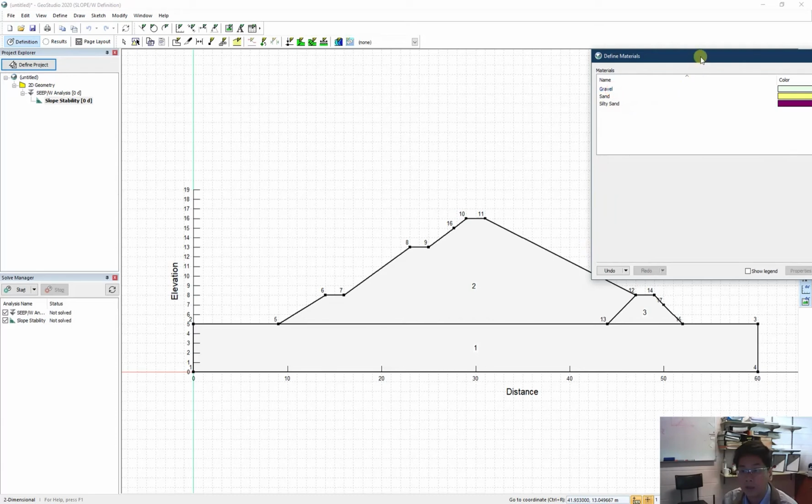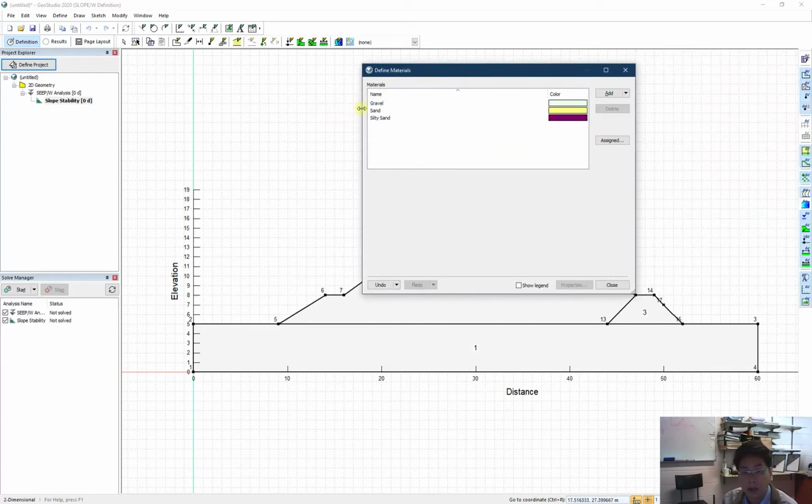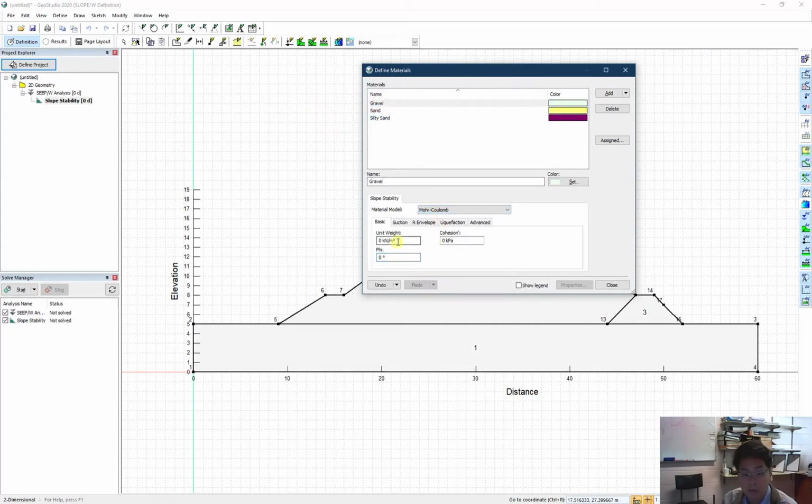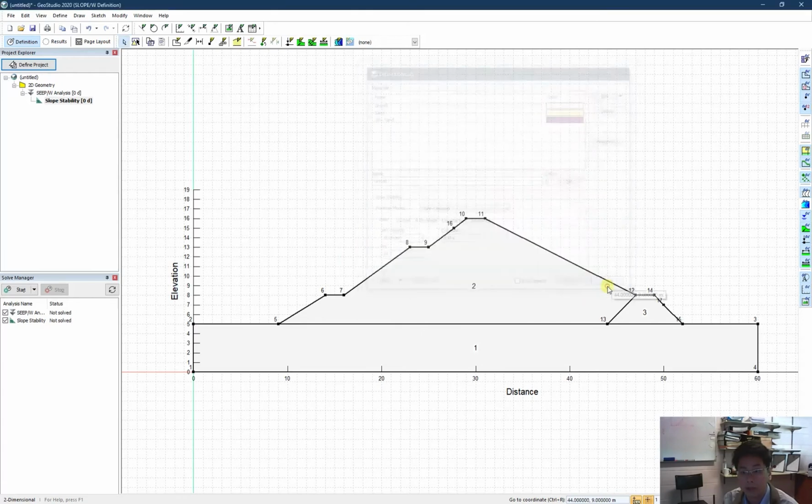Now the last one is the gravel. I need to set the Mohr-Coulomb for that. The gravel is about 20 kilonewton per cubic meter. The cohesion of a big material like this is very different. It can be 0, and mostly 0, because the big particles have angular contact and therefore no cohesion between them. But it has some geometrical resistance, but I will keep it 0 as normal. And here I set the friction angle higher, maybe 34. Yep, and that is the end.